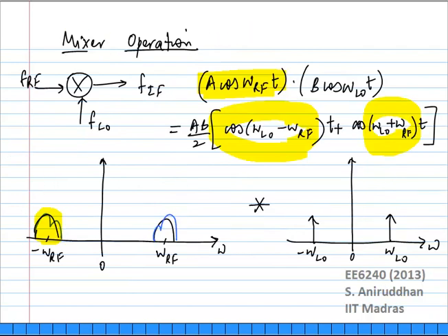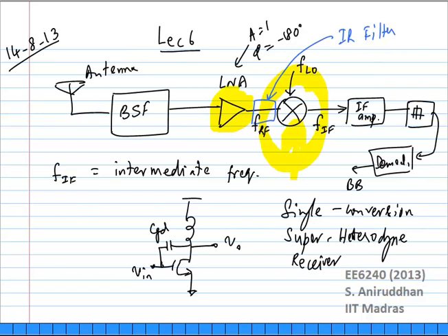For example, what I have not talked about here is digitization of the signal. I have not even put an ADC in the receive path. Any modern transceiver will have an ADC somewhere in the receive path. Question is, where do you put it? The best case of course would be to put an ADC right here. You just digitize the RF signal completely. Are there any problems with that? Difficult to design a high speed ADC. Anything else? Dynamic range of the ADC. Anything else? Noise. Anything else?